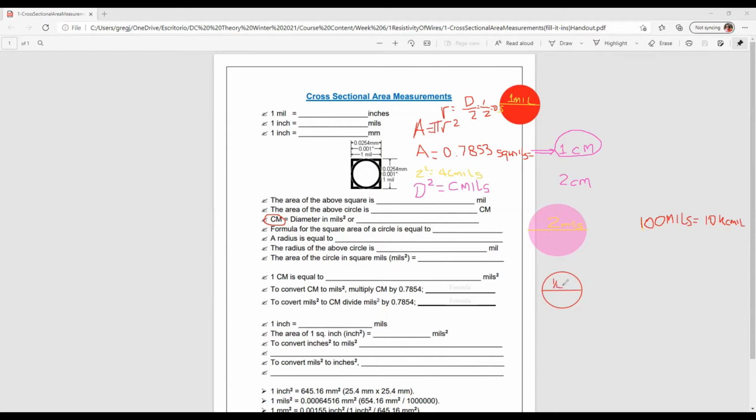That's the thickness of my conductor, 1/4 inch. So I'm going to have to convert this 1/4 inch into mils to find the diameter in mils. I can do a mental conversion. 1/4 means 1/4 of 1,000. In other words, 250 mils.